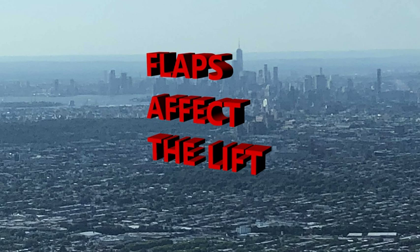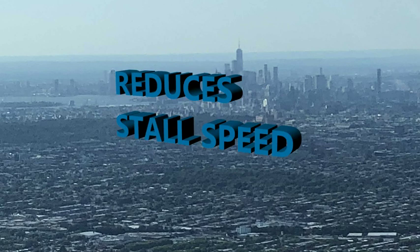When flaps are extended, and you can notice them if you've been around airplanes, they're increasing the surface of the wing. That also creates a more aerodynamic design, a curvature, which increases the surface area and creates lift. As a result, it reduces the stalling speed. So it helps when you need extra lift pretty quickly, which would be at takeoff and also